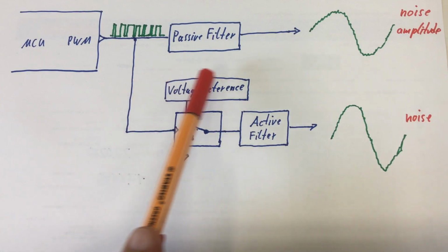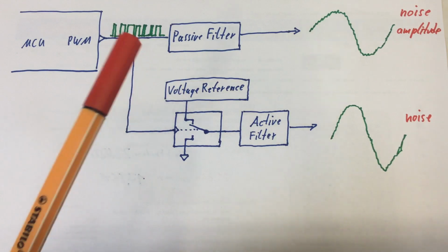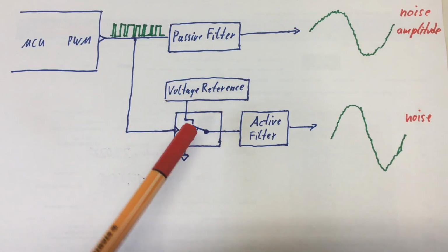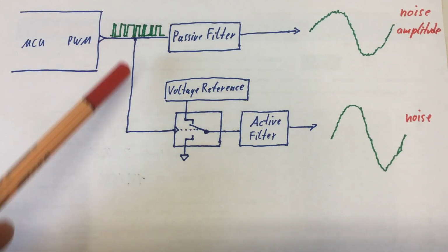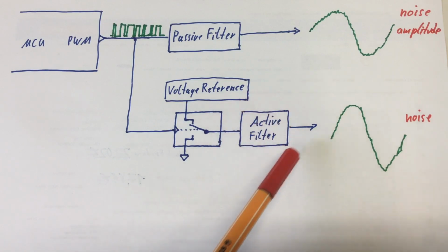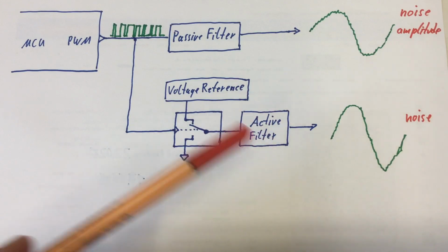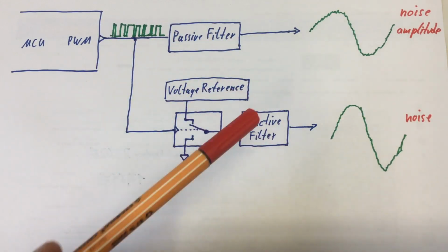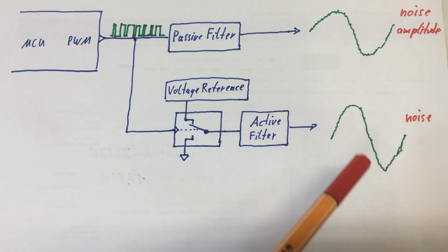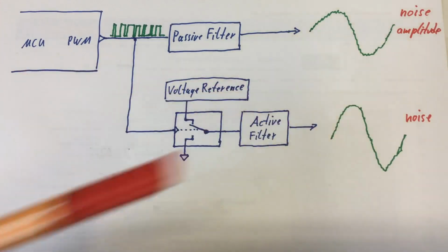All we have to do is to take a real voltage reference, which gives us a precise and stable voltage, and an electronic switch, aka MOSFETs, that is driven by our PWM signal. And then we add some active filters that can account for the dampening of your RC or LC elements. And we get, still with some noise, a sine wave, but with a stable amplitude.